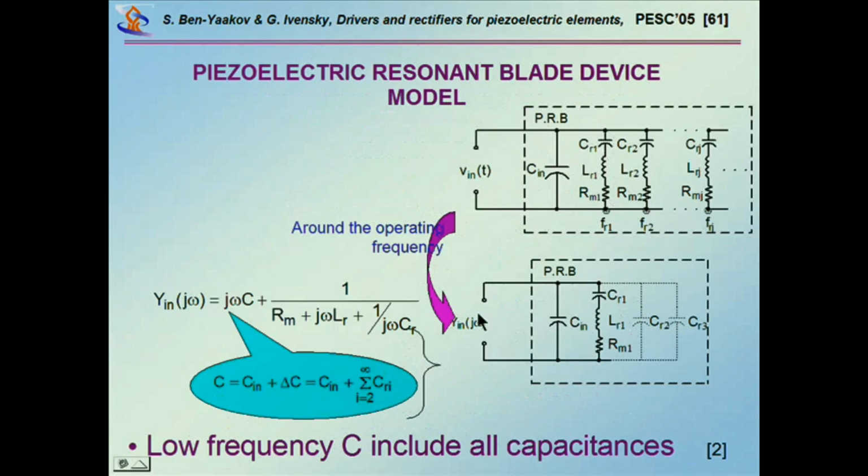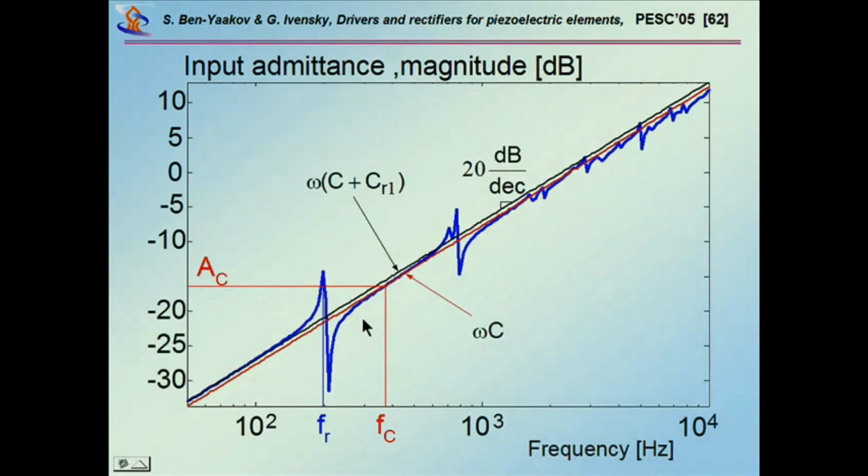Notice that the capacitance that we have is, as I said earlier, the dielectric capacitance plus these capacitances, because at a frequency which is lower than these resonances, the inductor is short, and I'm neglecting this resistance here, so we do have the contribution of the capacitance, okay? And then we can do some measurements and do a fitting to this part. There are various ways of doing it.